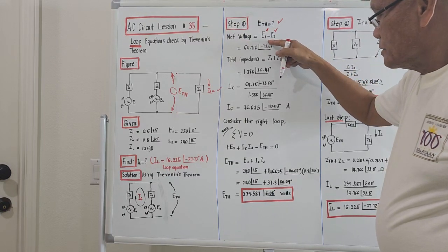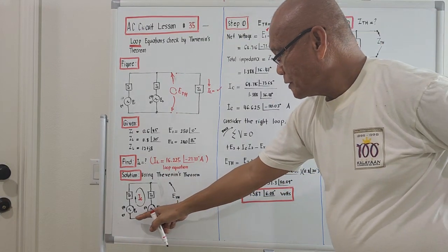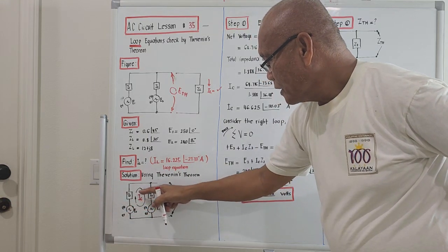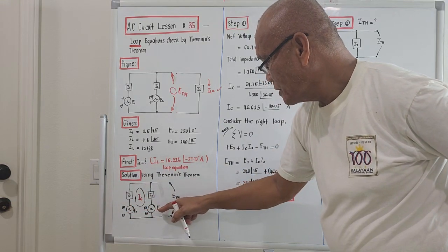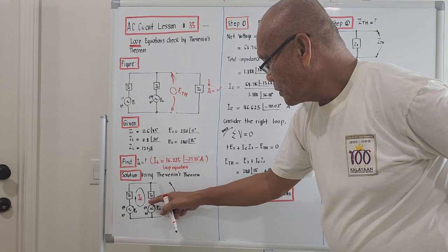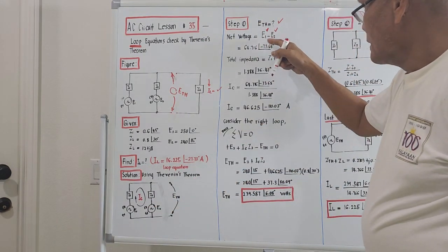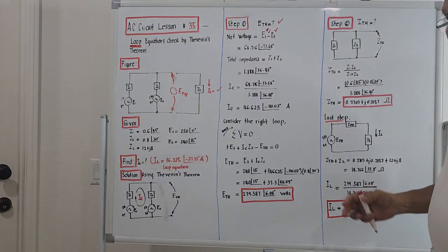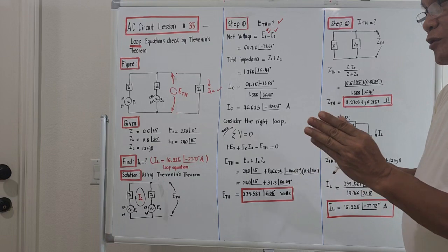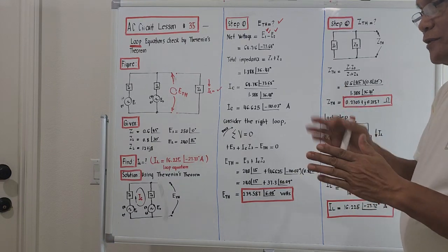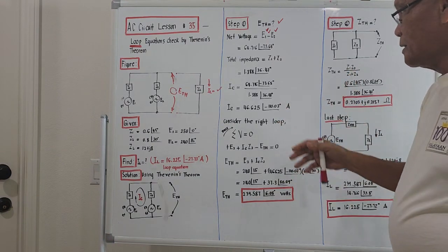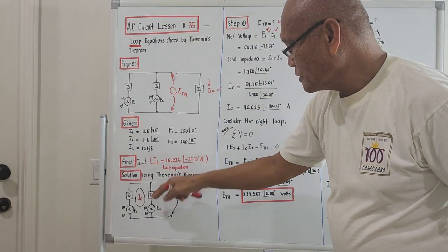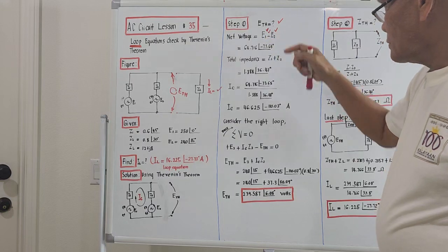It should be minus because their polarities are actually opposite. This is minus to plus, and when the circulating current passes through source number 2, it should be from plus to minus, so this is minus. They don't add up because they are in opposite direction, so it will be the bigger minus the smaller, it depends. With this given configuration, circuit tracing, it should be E1 minus E2.